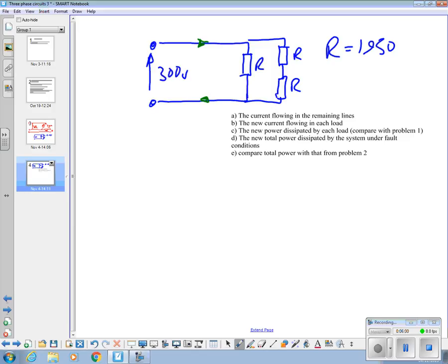They're the same, they're equal to each other. The current in the... because this was the red phase, this was the yellow phase. So if it's delivering current along here, it's travelling through that resistor network, some this way, some that way, but eventually all meeting up down there. Again, it's just a simple AC network now with one voltage source.